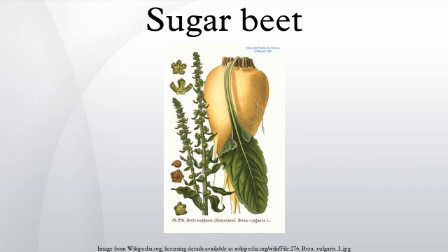Diffusers are long vessels of many meters in which the beet slices go in one direction while hot water goes in the opposite direction. The movement may either be caused by a rotating screw or the whole rotating unit, and the water and cossettes move through internal chambers. The three common designs of diffuser are the horizontal rotating RT, inclined screw DDS, or vertical screw tower. Modern tower extraction plants have a processing capacity of up to 17,000 metric tons per day.